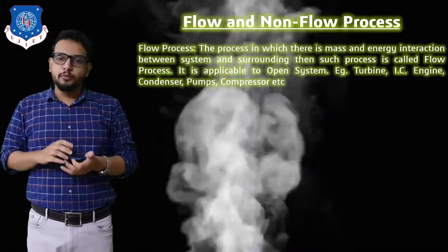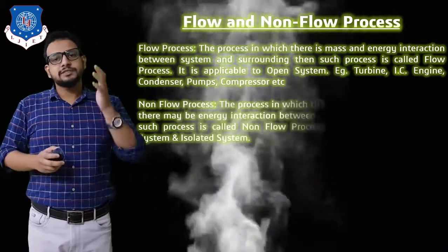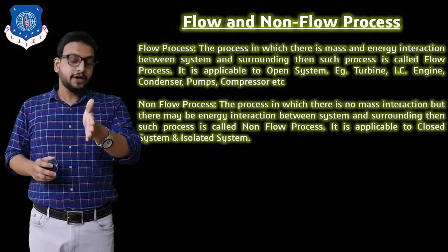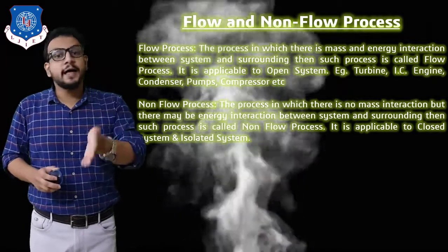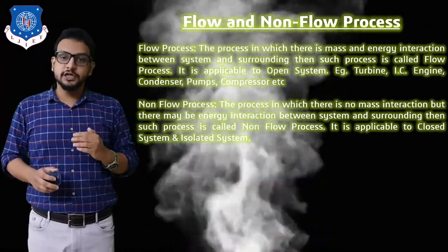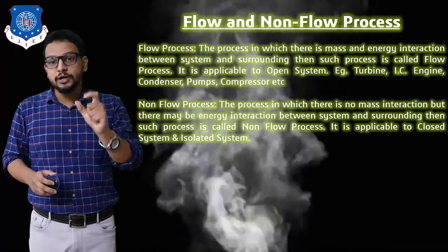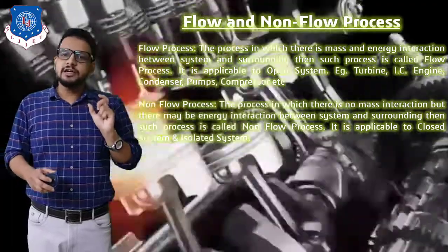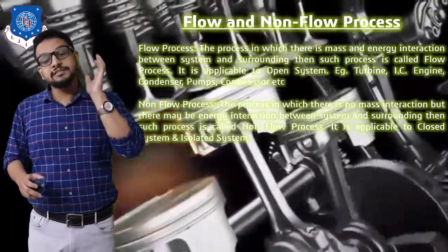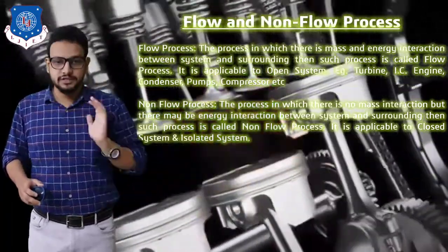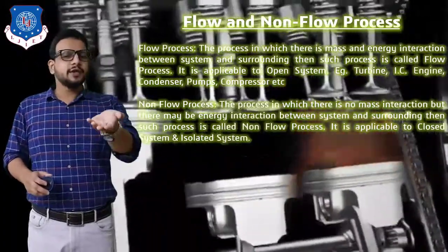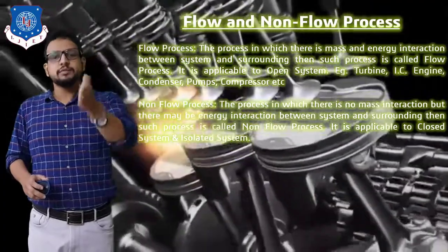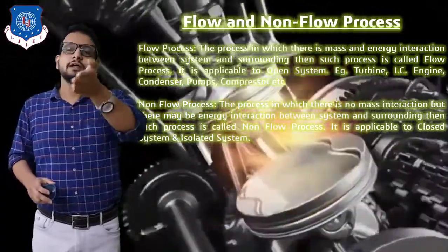Now, what is non-flow process? We would say the process in which there is no mass transfer across a system boundary, but there may be energy interaction or heat interaction. The most important term is "may be", which means there may or may not be energy interaction between system and surrounding. Then such process is called a non-flow process. On which system can we apply this process? It is applicable on a closed system as well as on an isolated system.